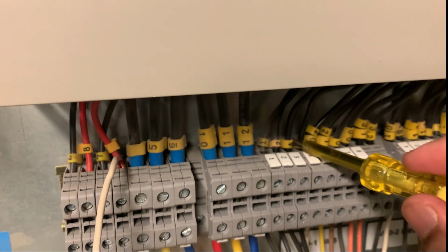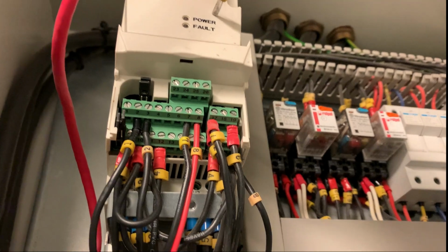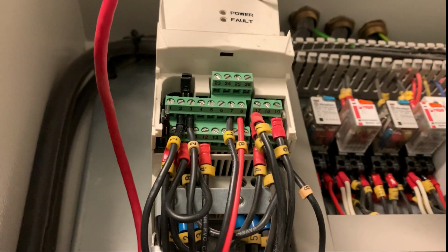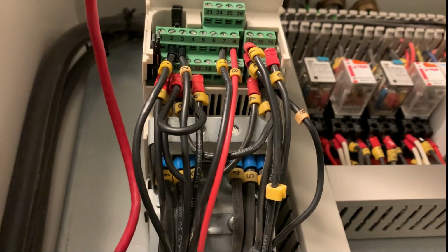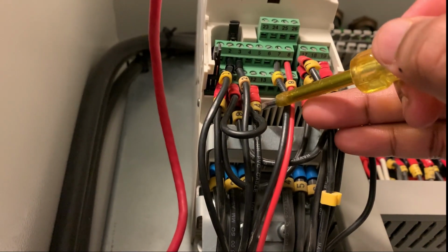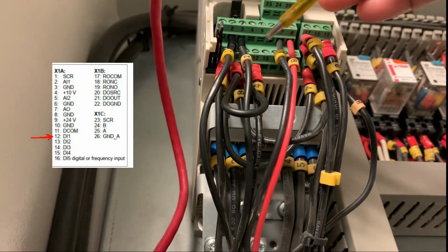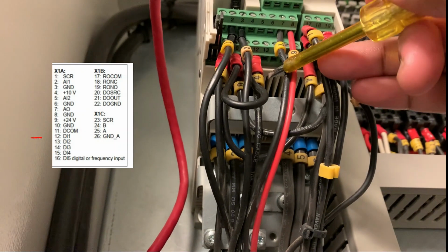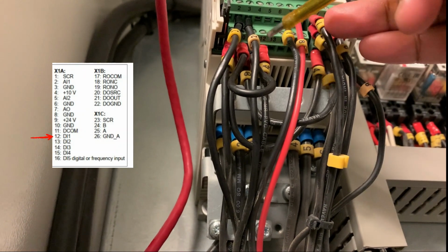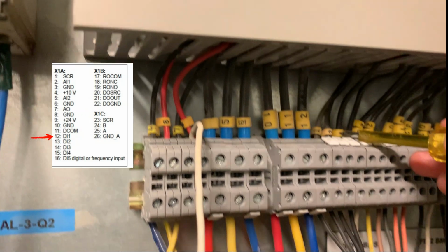Okay, and now let's talk about this 4, 4. When we want to run this motor, in my case, I have used this as a supply fan. So when there is a fire in the building, the fire will trigger this VFD. What I have done is, in the 12 number terminal, as you can see, I have connected a cable 4. This 4 means when there is a fire in our building, the fire will apply 24 volt to this terminal. When this terminal has 24 volt, it will run the motor. So this 4 is connected to the fire input.